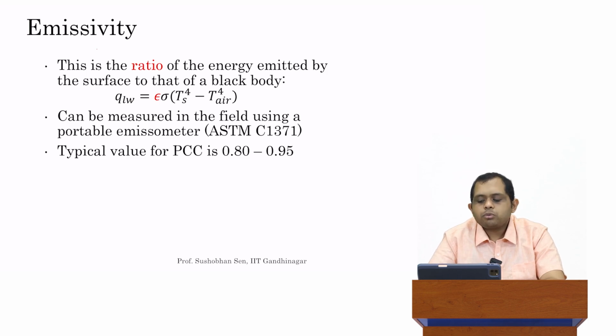Okay, the other optical property which we're interested in is emissivity. This actually goes back to what you may have studied in high school in heat transfer classes. I hope you studied this. As you know, any body whose temperature is above absolute zero Kelvin is going to absorb and emit some amount of radiation. A body which emits all the energy which is absorbed, that is a perfect absorber as well as a perfect emitter, is called a black body. Now, a black body is a theoretical construct. There are actually no black bodies in nature except perhaps black holes, but that's a different issue. There are basically no black bodies in practice on Earth.